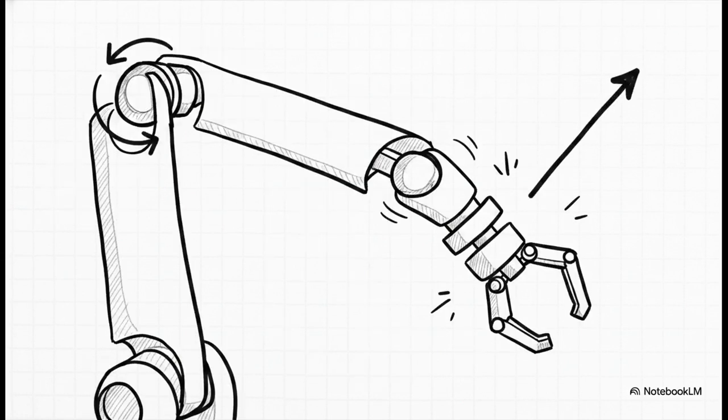So how fast is grip A moving from our spinning perspective? We take that local arm rotation we just talked about, the 2I, and cross it with the relative position vector. This cross product yields the relative velocity. The math crunches down to 2.2627 J plus 2.2627 K meters per second. This is exactly how fast the robot's arm appears to be moving if you were bolted to its spinning shoulder.